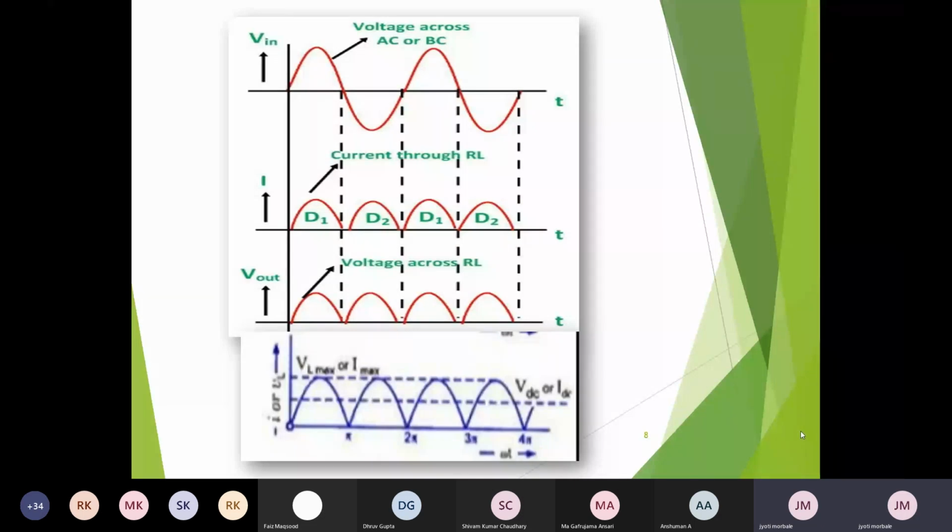That means 0.7 volts will be lost. I mean input voltage उतना lose करेगा because this much is the barrier potential for the diode. So 0.7 volt तो diode के across ही चला जाएगा, and the remaining voltage will appear across the output load resistor. So these are the waveforms where you can show the input and output signals.